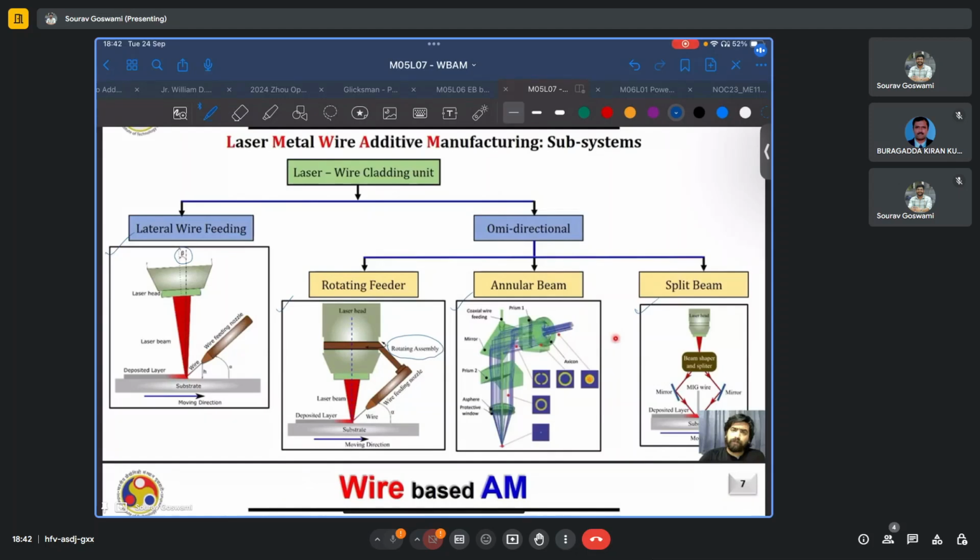So we know that typically the angle of incidence equals the angle of reflection. If the laser beam were to fall normally on the surface, and especially if the surface is highly reflective, as is typically the case for metals, there is a chance that some energy will be reflected back, and that reflected energy can in turn damage the laser optics.